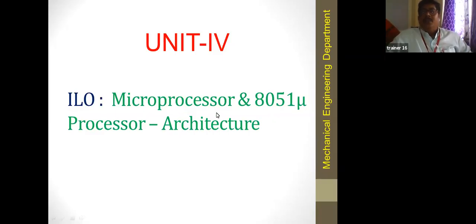Next we discussed the OR gate. The OR gate also has two inputs A and B, and the output is the sum of the two inputs, Y is equal to A plus B. Next we discussed the NAND gate. NAND is the combination of two gates, the AND gate and the NOT gate, so here also two inputs and only one output.